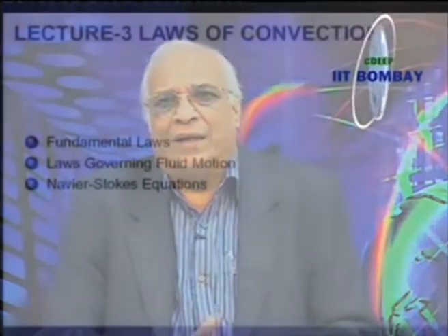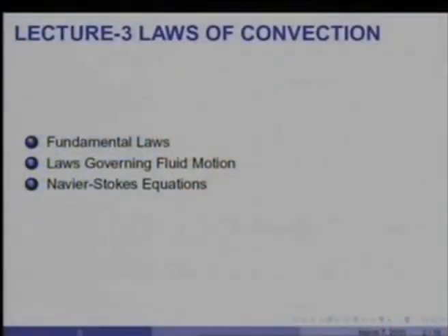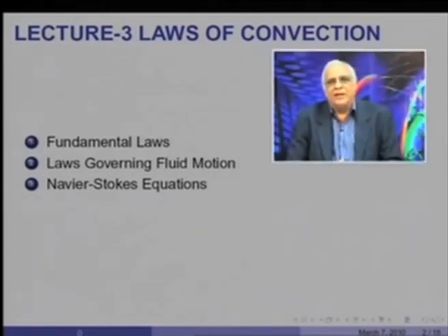In a way, this is the most fundamental lecture along with the next one, because I will first be stating the fundamental laws that govern our subject of convective heat and mass transfer, but then go on essentially to enunciate the laws governing fluid motion, which are then also the tractable forms of governing equations, also called Navier-Stokes equations. So, I will end with complete derivation of the Navier-Stokes equations.